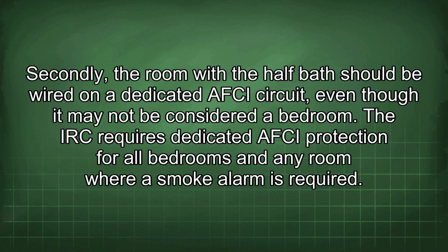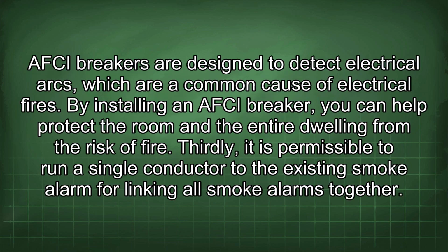The IRC requires dedicated AFCI protection for all bedrooms and any room where a smoke alarm is required. AFCI breakers are designed to detect electrical arcs, which are a common cause of electrical fires. By installing an AFCI breaker, you can help protect the room and the entire dwelling from the risk of fire.